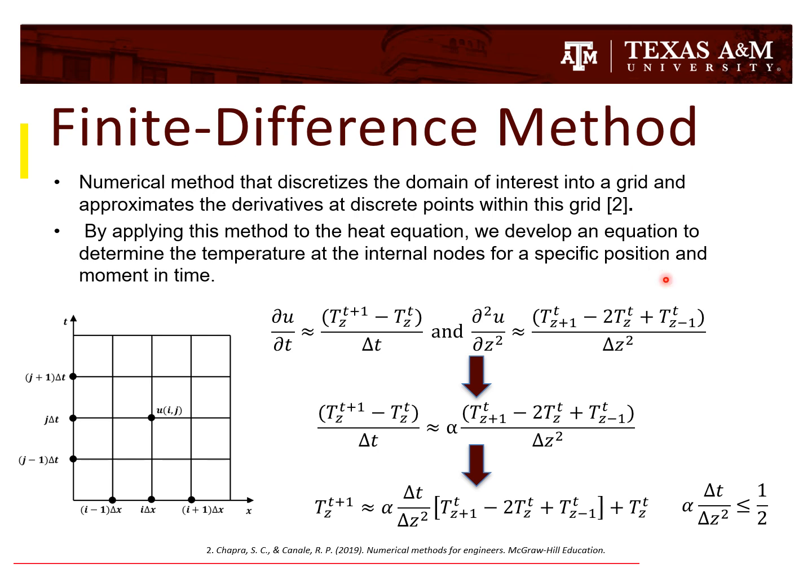As can be seen in the slide, the final equation, which gives us an update for the temperature at every internal node, can be seen at the bottom. Basically, this gives us a way to predict the temperature at all of the nodes within our sample that are not the boundary nodes.